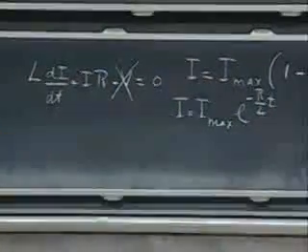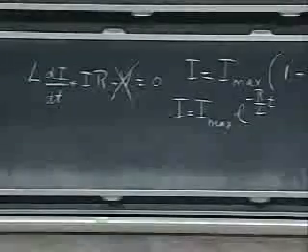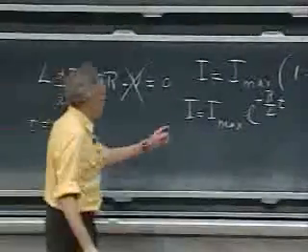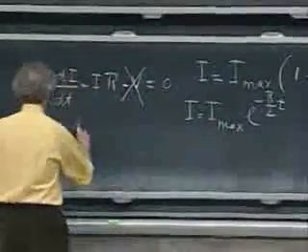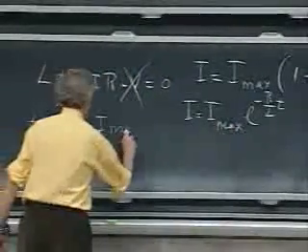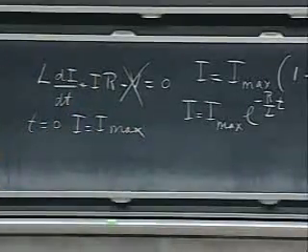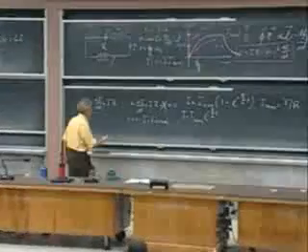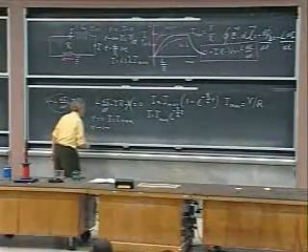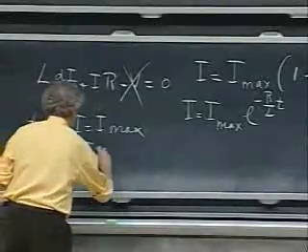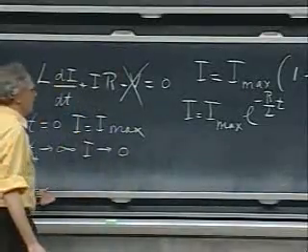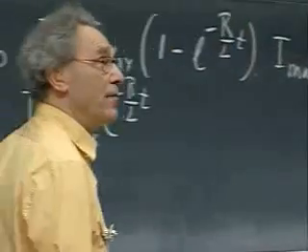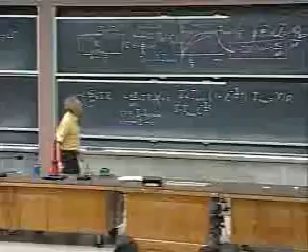And that exactly has all the quantities that you wanted to have. Because notice that when you put in t equals 0, the current is indeed maximum. And that's what you require. That's the moment that you make that capital V 0, the current was still running. But notice that when t goes to infinity, you wait long enough, the current goes to 0. And if you wait L over R seconds, then you are down to about 37% of your maximum current.